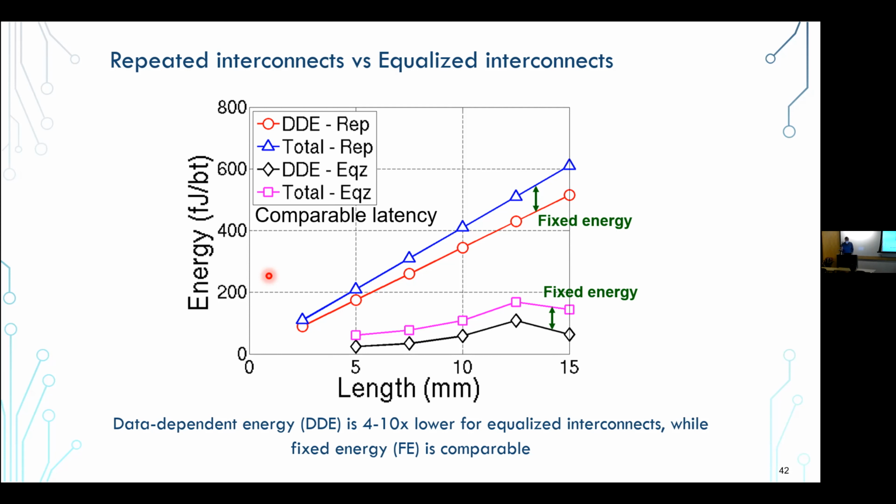That's also some consideration people want to have, because people in general want to have an idle network burning zero power, right? And then a full throttle network burning the max power. But if you have a lot of flops and clocks and everything in the network, that's not necessarily going to happen unless you end up gating those flops. That's another technique you can use, but it requires state control and things like that.